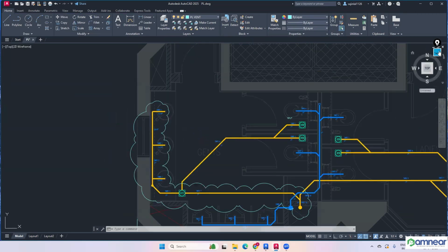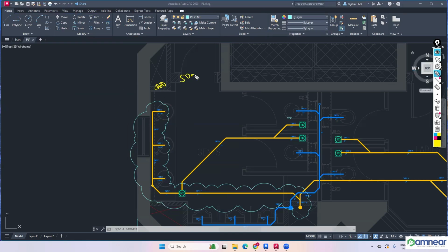Okay, normally what people will be doing. For example, if this is a 50 mm schedule 40 pipe, let's say this one, they will have the middle line. Then from there, they will offset 25 mm on the right side and left side. Accordingly, you can make it like a 2D. But when you are making the fittings and all, that will be very difficult. Also, 50 mm schedule 40 PVC plastic, it doesn't mean that.